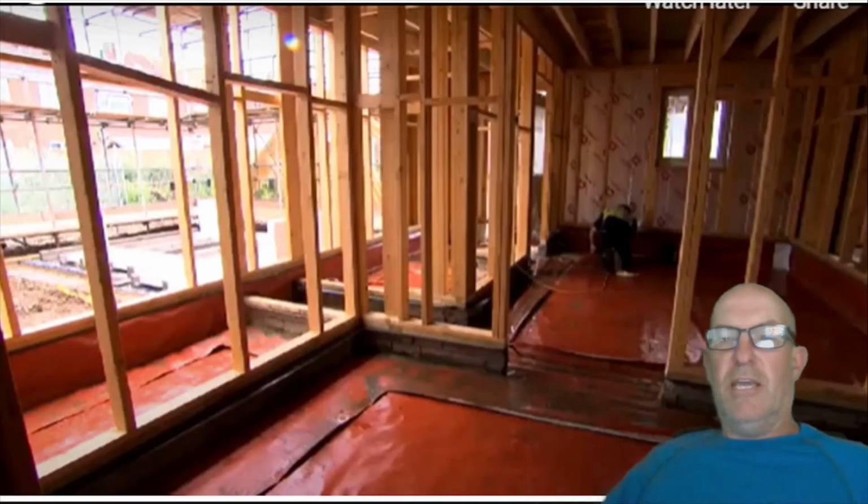And as we can see, we're back in a timber frame structure, and we can see the condition of the membrane there. It's lived through quite a lot going on, not just the weather, but other occupations, the timber framers, the roofers, the tilers, and as we can see, when the infills come in, having a clean area and an undamaged area is quite critical at that point. So again, how we incorporate our sequencing of work is quite key.